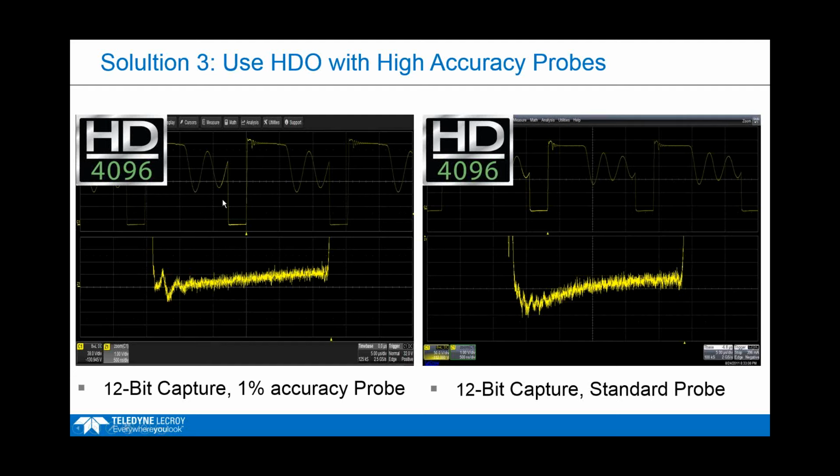The HVD probes go up to 120 megahertz, so you're maybe borderline there, but it should hopefully be enough bandwidth for what you're looking at, depending on how fast the switch is. There are some new kinds of switches coming out now that add more of a challenge, but they are not widely adopted yet, like gallium nitride. The wide band gap materials switch a lot faster, so it's very hard to measure those on scopes these days, because you often have a bandwidth limitation.